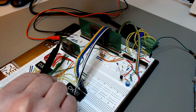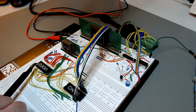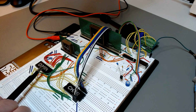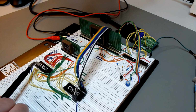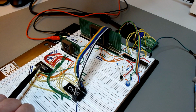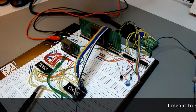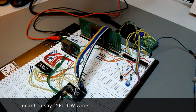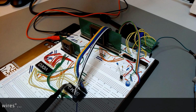With that clock, Kavya will just scan through all the character tokens in the token memory, line by line, 16 times per line. Each time an address is provided to the video memory here, a token code will come out through these white wires here to the character memory, and those provide the 8 most significant bits of the character address.